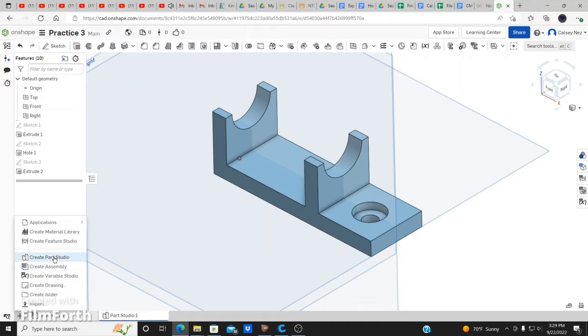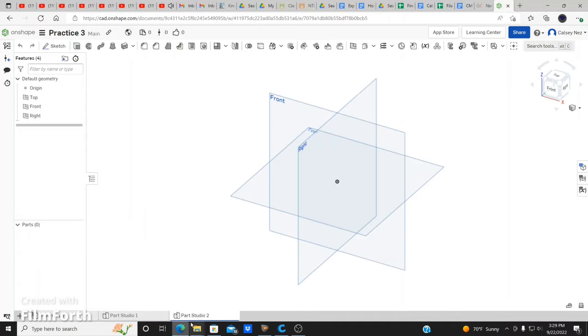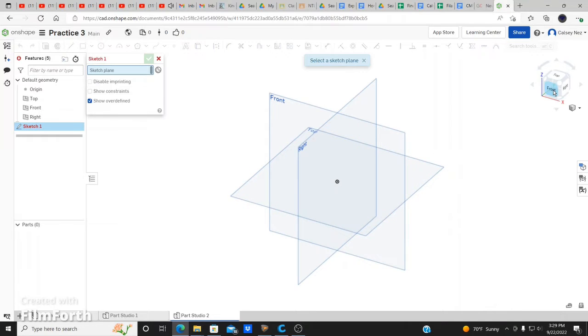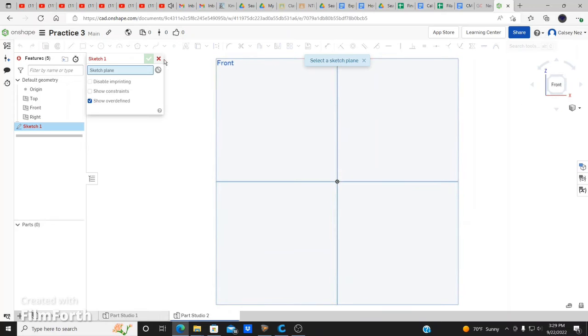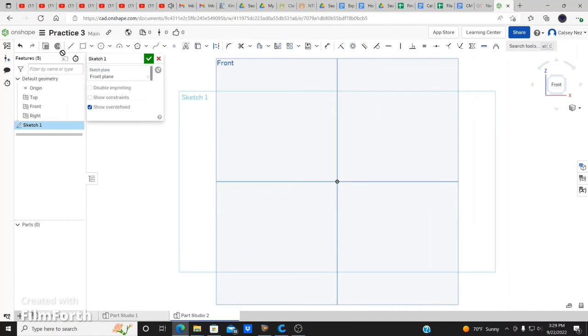So we're now picking up the pace to actually begin our first other dimension and drawing. So what I'm gonna do is go to my next drawing, and this one's gonna be easy. So I'm gonna do my sketch, front plane. I'm going to create my center lines. I'm gonna click the line and center line. I'm gonna select this origin right here. I'm gonna go straight horizontal. That's it. There's no dimension. Don't worry about anything else on this guy right here.